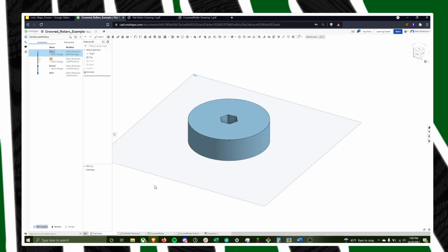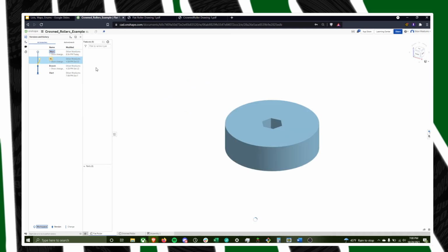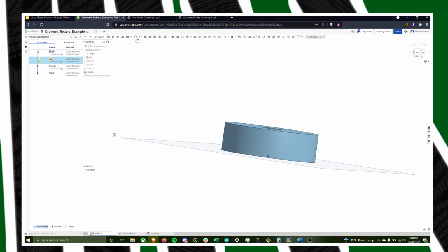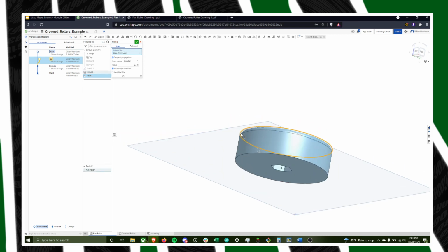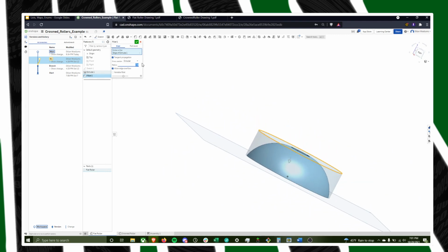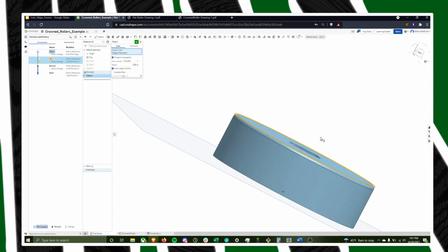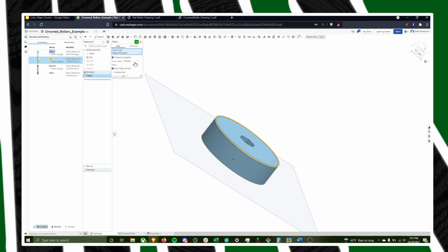The other thing I want to show is this is a good part to show it on. I'm actually going to flip over to B1 for this because I don't want these changes to be saved really. Is fillets and chamfers. We use fillets and chamfers all the time. So a fillet, you click the fillet button, it gives you this entities to fillet, and you can pick a radius. Larger radius means you end up with stuff like that. Tighter radius means it just barely takes that corner off. That's a fillet. It's a rounded corner with a radius.